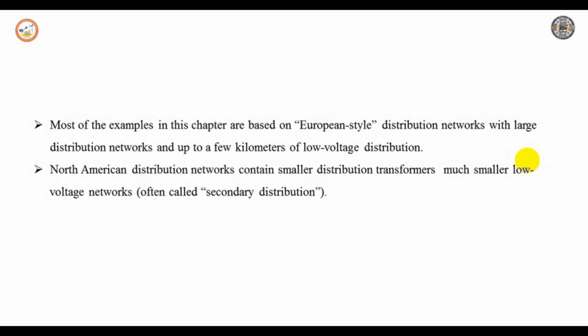So this value, PST, is normalized to 1 to represent a level of voltage fluctuation which may be sufficient to cause a noticeable flicker to 50% of a sample observing group. Another measure, called long-term flicker sensation, is often used to verify compliance with compatibility levels, which are established by standard bodies and are currently used in utility power contracts. This value is a long-term average of PST samples.